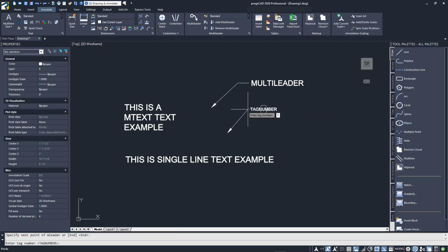So why are they called multileaders, you ask? Because I can add or remove leaders to or from the MLeader object. From the panel, I'll select Add Multileader and select the one I want to alter. Just move your mouse to add as many new leaders as you like. Plus, I can remove them in the same manner with the Remove tool.